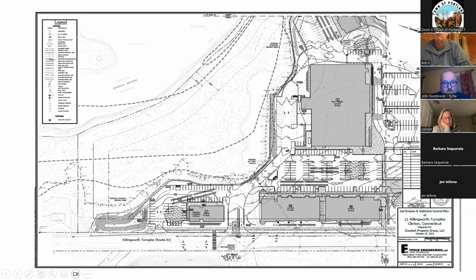These are contour lines. What is this? A drainage basin? Very good, that's a drainage basin. It slopes down, and there's a flat bottom to this drainage basin. A lot of the stormwater will be piped here and will settle in and infiltrate in that basin right there. And it's got pretty steep sides.